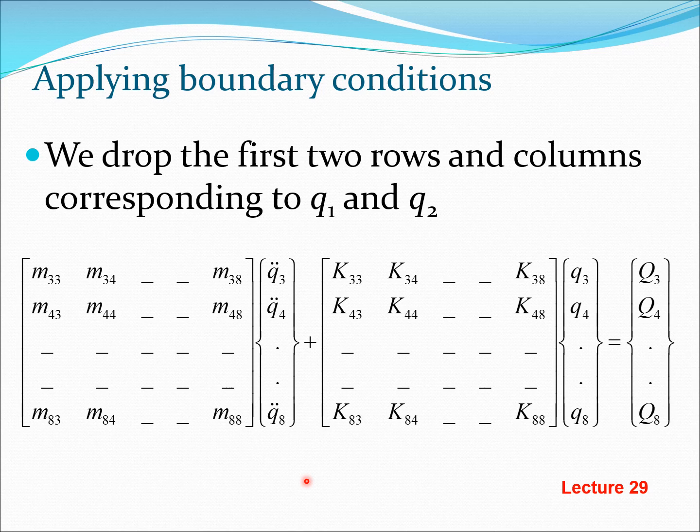We did it in a very clever manner. And of course, one thing you will note is that the element we have constructed here does not necessarily satisfy the force boundary conditions because we have only access to Q1 and Q2. So essentially the displacement and slope in terms of the degrees of freedom, we don't have access here to the moment and shear force. So we are going to apply the geometric boundary conditions and discretize this mesh sufficiently well and hope for the best in terms of satisfaction of the force boundary condition.